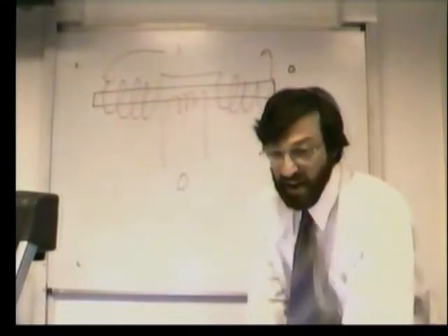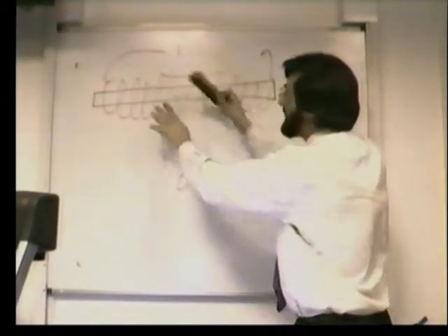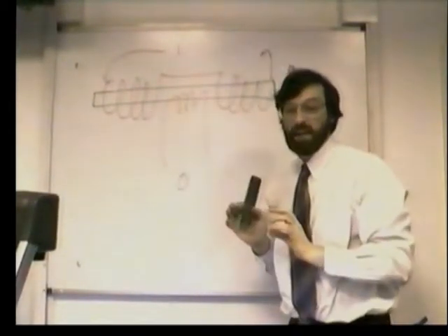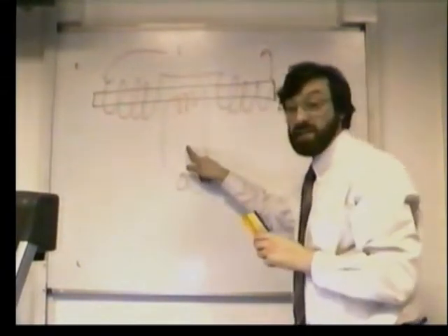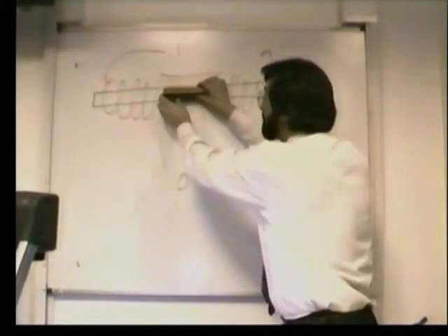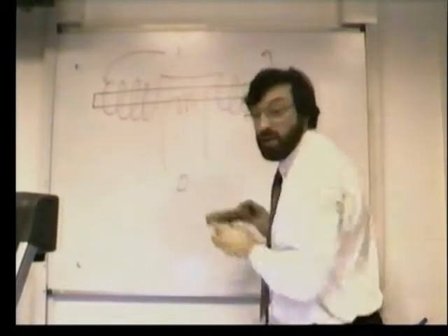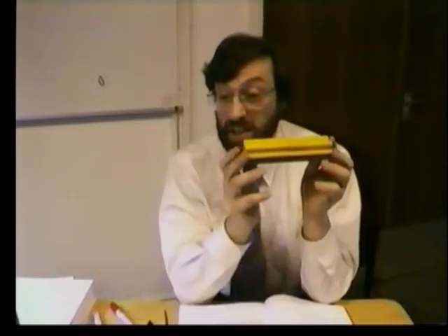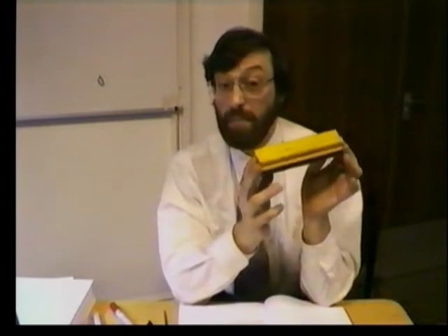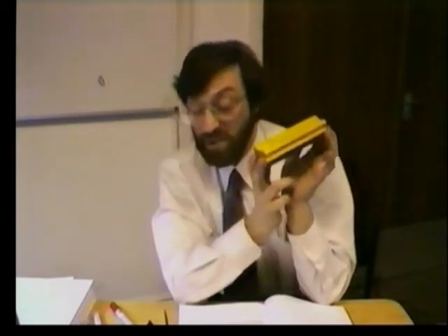if our ferrite shaft, here we have our ferrite shaft, was to move one way or the other off center, there would be an imbalance. And it can be shown that the change of current output on the secondary is directly proportional to the position of the inner core. So precise is this mechanism that LVDTs can measure movement less than a micron, less than a millionth of a meter. They're incredibly sensitive devices, very, very widely used.